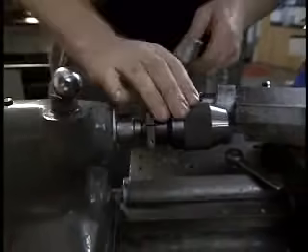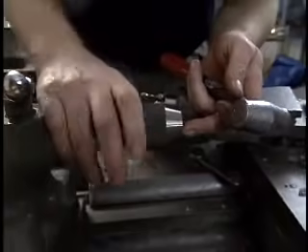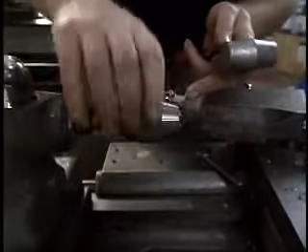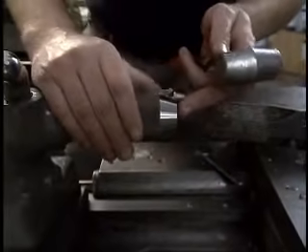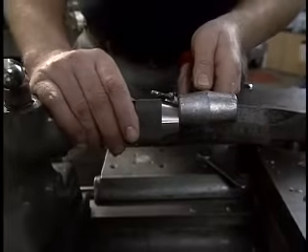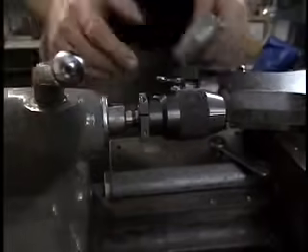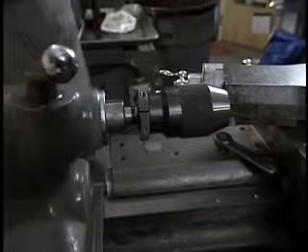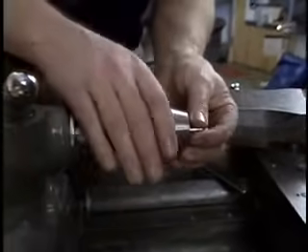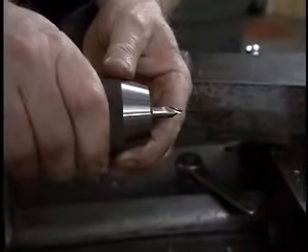with a soft hammer, with the jaws of the chuck that are normally extended drawn back inside the body of the chuck, very lightly tap the chuck to seat the taper into the tailstock. Now we're ready to start drilling the hole.